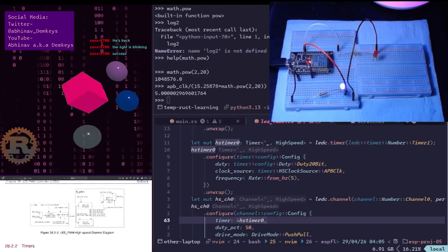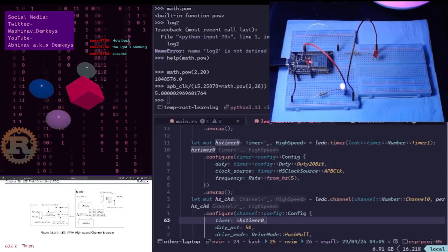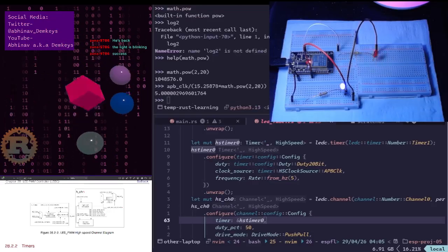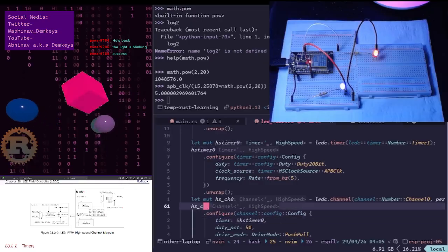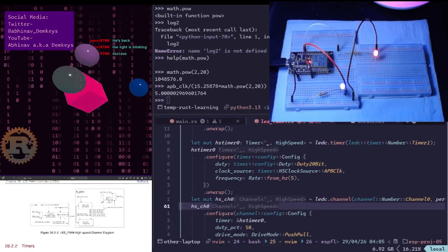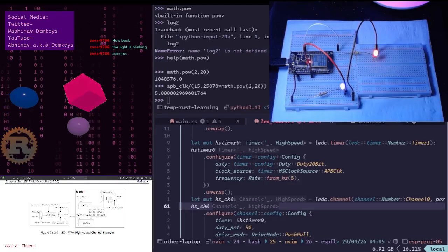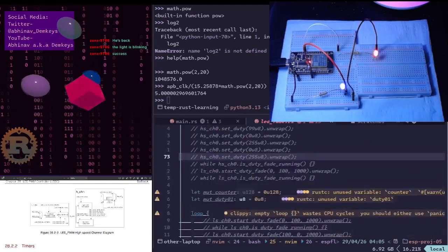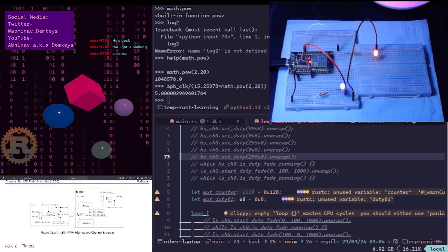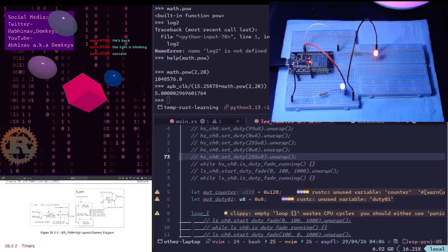Yes, the light is blinking, and the amazing thing is that we are doing this by, hold on. Here, the only thing we are doing is that we have configured the high-speed channel. This is being done through PWM, pulse width modulation. We are not doing this using the LED on-off toggles. Or, well, we are not doing this by calling the LED toggle function and using time-based methods.